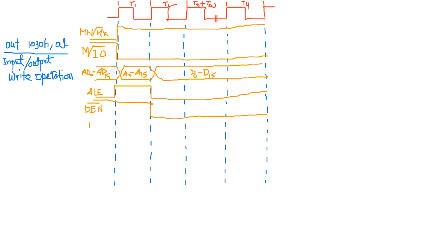Data transmit/receive, DT/R. So look at here now, it is a transmit mode or receive mode. Data is moving from the microprocessor AL towards the port, or if it is related to memory also. So from the microprocessor, data will move. So that means it is in transmit mode. Okay, so that means it is high the whole time. All the time it is high.